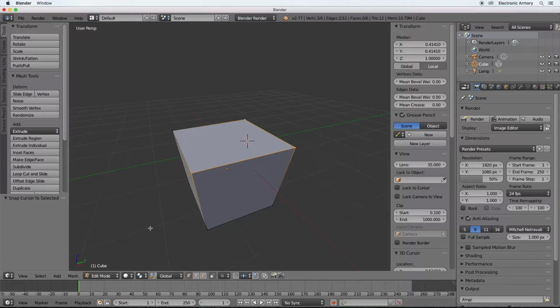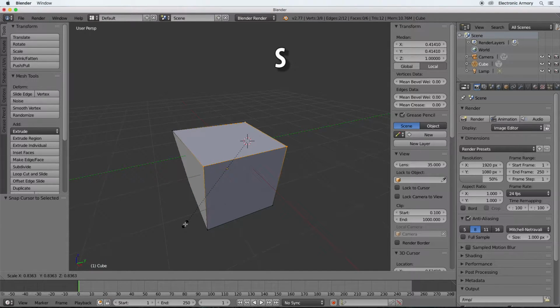It's an extremely powerful and helpful tool that we'll get into a little bit more here, but a lot more in later videos. For now, go down to the menu at the bottom of the 3D view, the one that looks like two white circles, and select 3D cursor from that menu. This is the pivot point menu, and in the case of scaling, it controls how things are scaled to and from. This works with rotation too, and you can imagine how that works since it has to do with pivoting. Try it out and play with it a little bit. With the 3D cursor option selected, scale your vertices using the S key again. You'll notice nothing has changed.